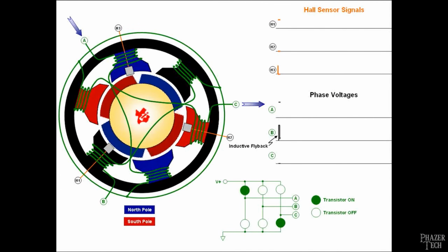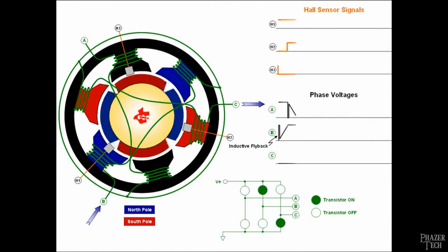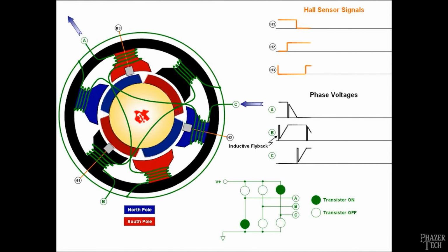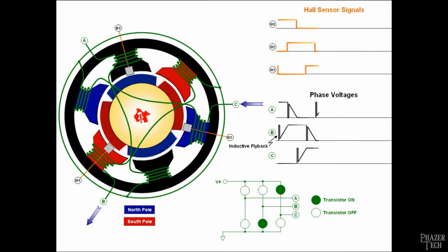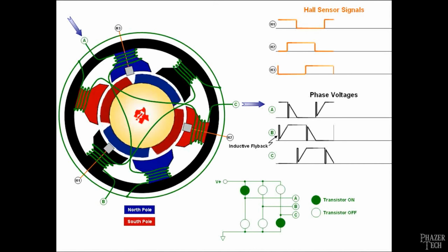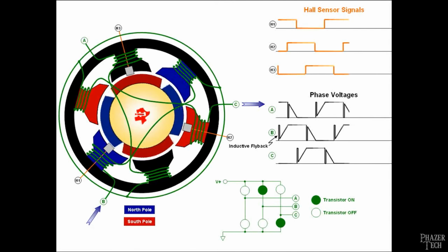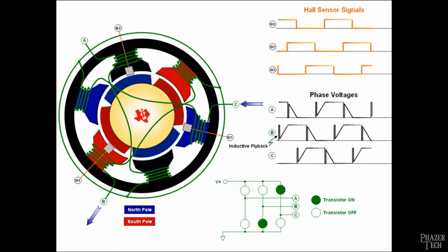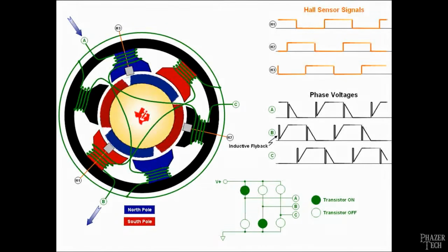Like I mentioned, the coils are constantly switching their polarity back and forth, and they need to do this at very precise timings. Unlike brush motors, where this mechanism is directly baked into the physical design of the motor with the commutator, brushless motors require an external electronic controller to manage the timings of all these coils. Most brushless motors also include several Hall effect sensors in order to keep track of the position of the rotor. All these things I mentioned not only add to the total cost, but also add complexity not just to the design, but also from a control perspective.